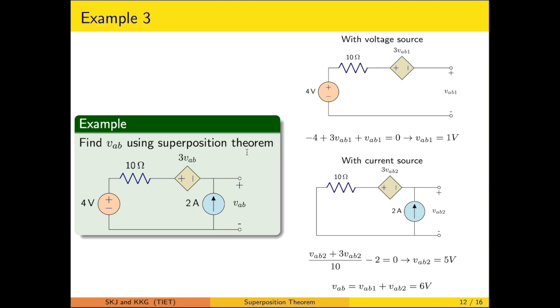When the voltage source is considered alone, the current source is open circuited, so that particular is removed. Now here there is no interconnection, so there is no closed path, that's why there will be 0 current in this. However, the KVL still holds true, so that is applied around this particular closed path.